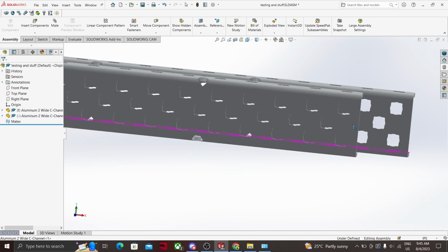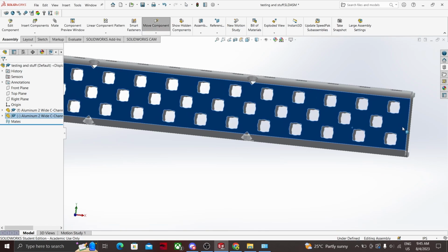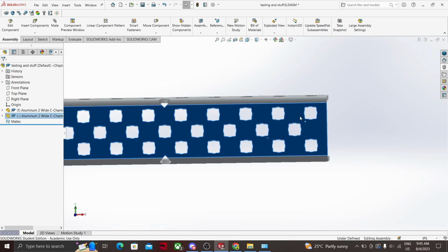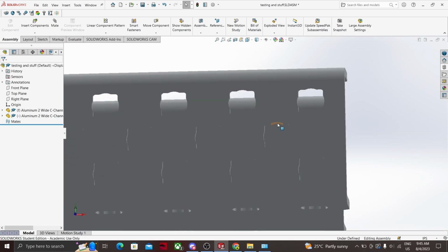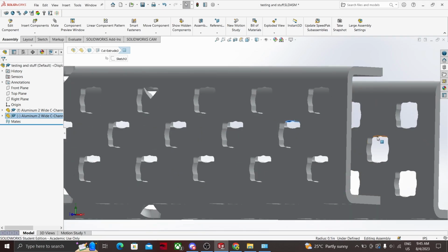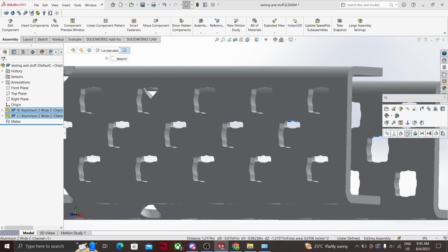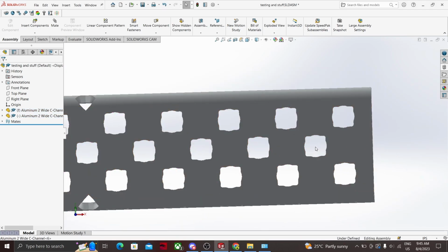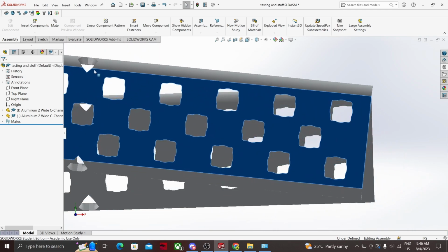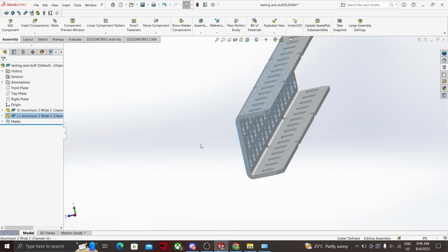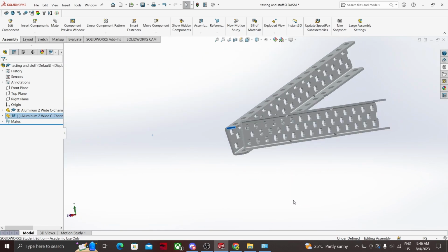Right now, we can see that when we want it lined up, all these holes line up with each other. So we can click this arc right here, which shares a middle point right here, and this arc right here, and we'll click the concentric mate to make them share the same middle point. And right there, you see these two arcs will be lined up now, and it actually kind of acts like a joint right now. You can rotate around it. It's a little confusing because I'm moving in 3D. Wait, let me get an angle.